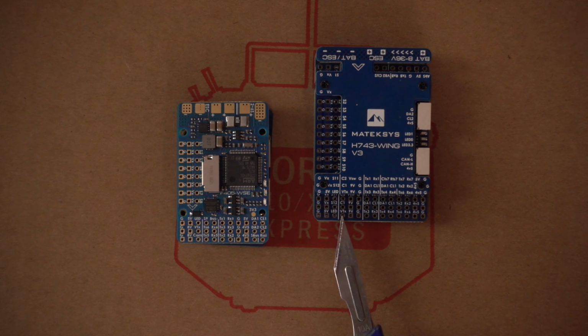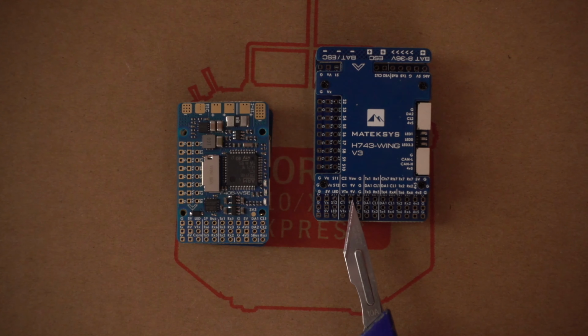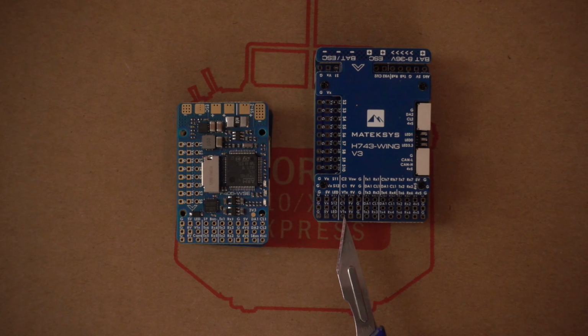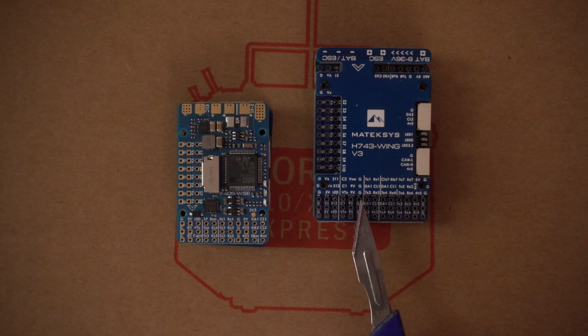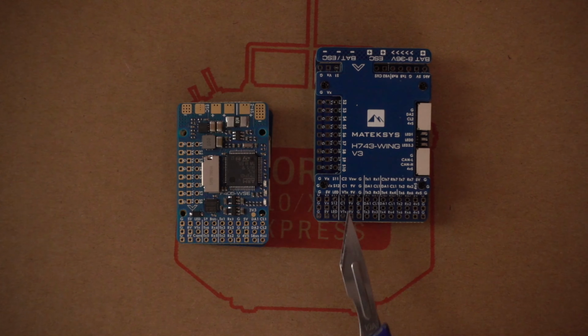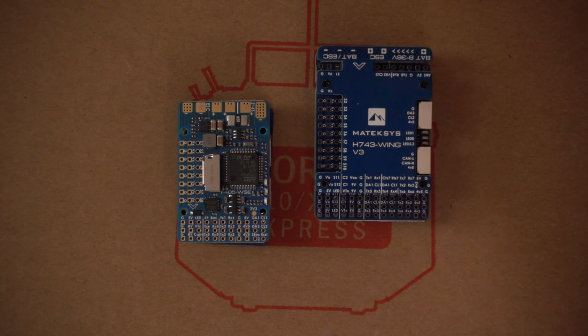Underneath that we have VTX, which is the video out to the video transmitter, and again we have this time 2 9-volt pads rather than the 8 volts, and 2 grounds. And at the top it says VSW, which is actually a switchable power. So you can use that to power off. It's actually running at the same power level as these pads, but you can switch it on and off. So if you're going to do that with anything, it'll be better with the VTX. Then if it's sat on the ground, you can switch the VTX off so it doesn't start overheating. But that block here is for our camera, same as this block here is for our camera. And to be honest, for most of what we're going to do, that's all we really need to worry about.